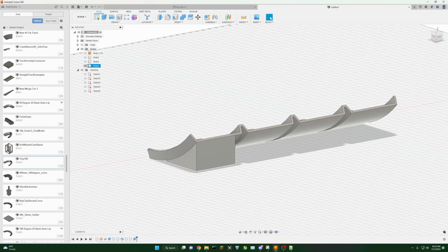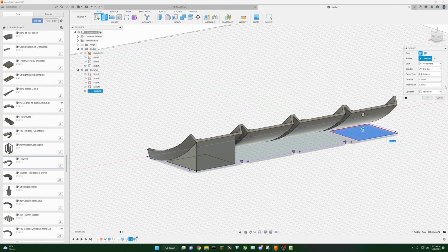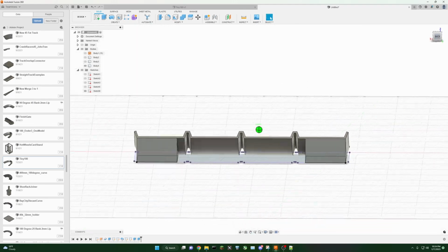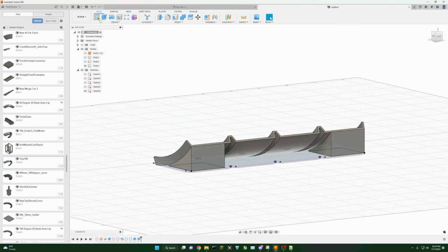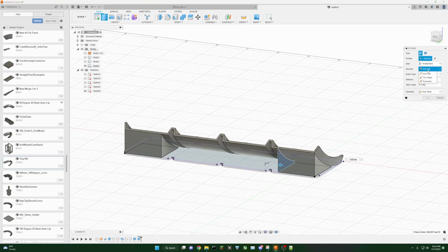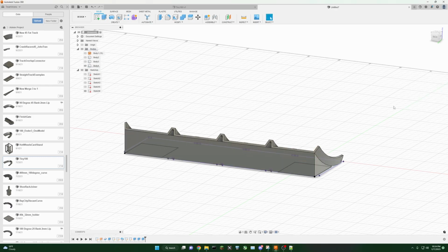We're going to bring this other sketch back. We're going to do this again. Okay. And you know what, might as well, let's just make it all the way across. We'll just go ahead and extrude this guy all the way across here. Change our extent type to to object. We go over there, join, it made it all nice and solid.